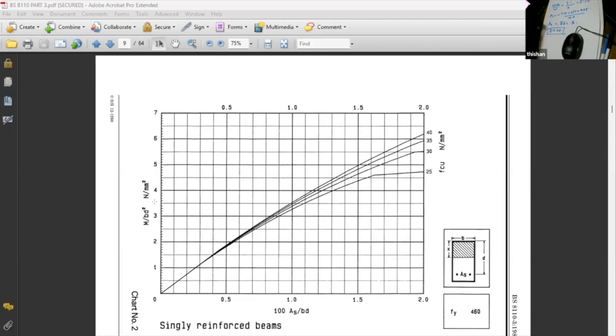If you need, say, 200 millimeter square of steel, then you have to provide it. So select the correct welded mesh. That's all. Welded mesh has no special rule. You calculate the reinforcement and use the same area from the welded mesh.